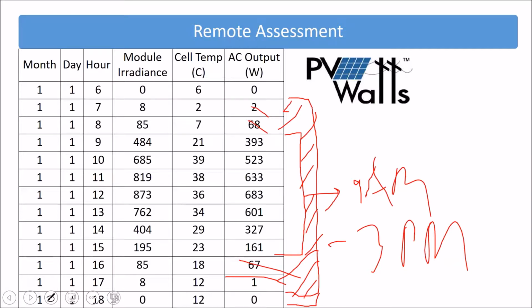So shadows can actually move south as well as north, even though you're in the northern hemisphere. And so it's always good to examine, say, if you're doing things by pencil and paper, what is my shade condition at the extremes? So at winter solstice, what does my shade look like? At summer solstice, what does my shade look like? And even spring equinox and fall equinox. And also not just what the shade looks like at high noon, but at the start of your significant production.